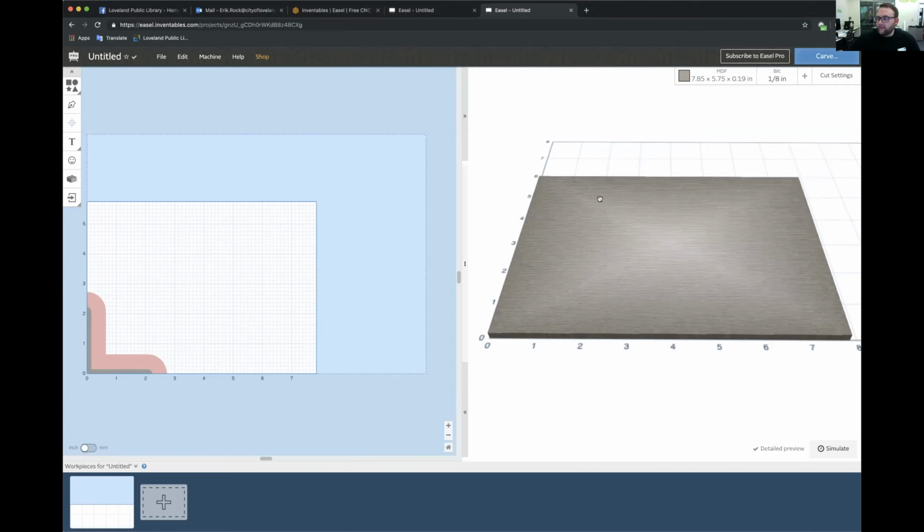So in a little bit, I'm going to actually turn the camera on. I'm going to tilt the screen. I'll let you watch me set up the clamps, but just know that we really are going to have about a half inch to a full inch on all the edges that we are not going to be able to carve. Okay. And that's just the limitations of the machine. It has to be able to hold the material down, so we can't carve over the clamps, you know.